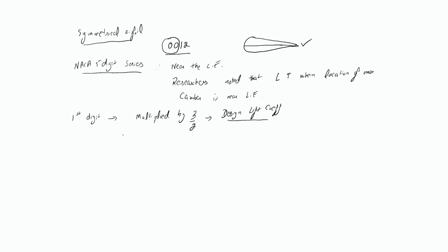This is the lift coefficient at the angle of attack for normal level flight, and which is usually around 2 to 3 degrees. Alright. Now I have taken the name of angle of attack, so I need to explain what exactly this is.